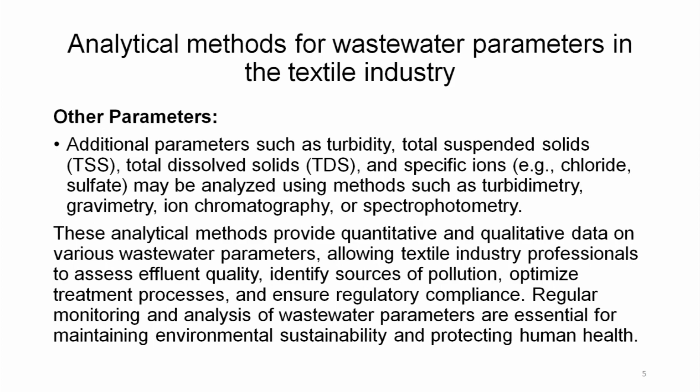Other additional parameters such as turbidity, total suspended solids, that is TSS, total dissolved solids, TDS, and specific ions like chloride, sulphate may be analyzed using methods such as turbidometry, gravimetry, ion chromatography or spectrophotometry.